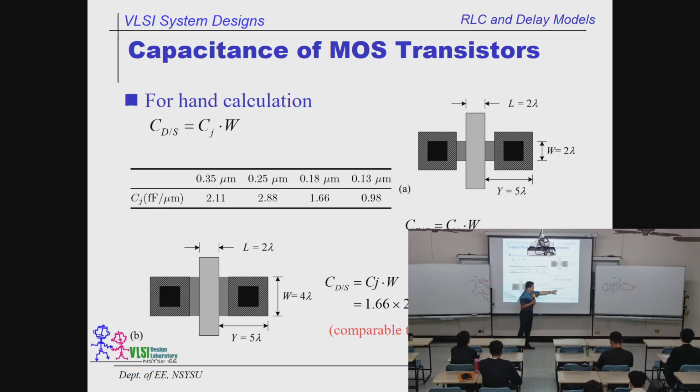It's about 0.6, relatively big, because the one created by the MOS is about 0.86, right? So they are close. So you cannot ignore the parasitics generated by the diffusion, because these numbers are close to the capacitance of the gate. All right? So it's not hard.